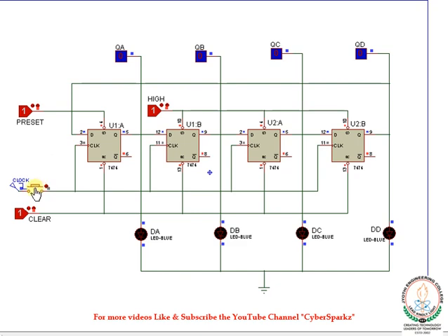You have to remember the concept that I have already told. The counter is not self-starting. So from the 0000 state, the circuit will not change its output even if you apply a clock pulse. So now to start the counting operation, we have to manually set the counter to its initial state or any valid state. So I'm going to set the first flip-flop, so that the counter output is set as 1000.